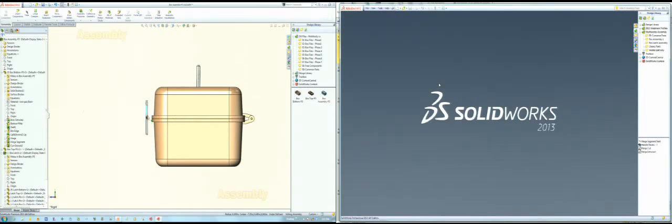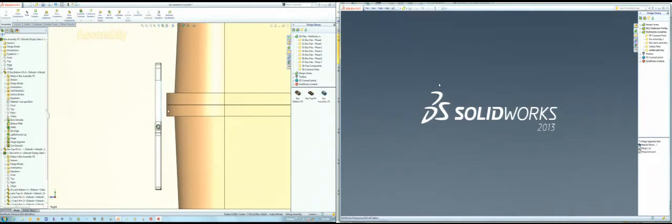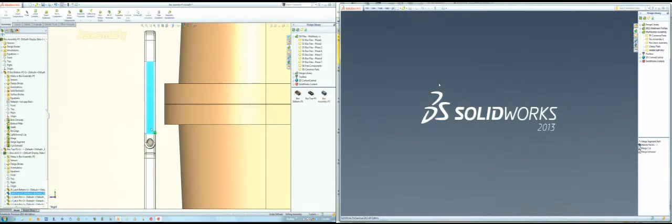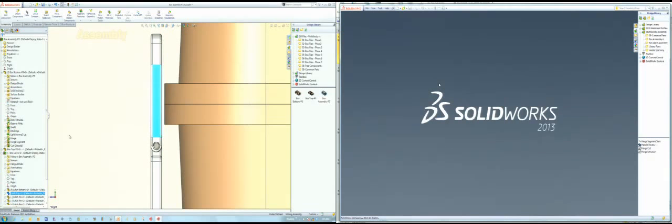But what I'm going to do is use this as a guide. So I know it's got to have a little separation from the side of the box, so I can position it wherever I need it. One nice advantage when I'm in an assembly, if I want to hide a component, I can just put my mouse cursor over and hit the tab key and I can hide.